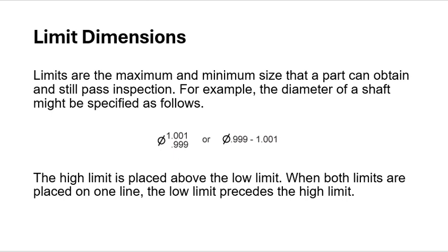So here, in this example, your part is a shaft, and of course your tolerance limits are for the diameter. Why do you know it's a diameter? Because of the symbol, and don't forget to review the symbols. Here, from here to here, it's telling you very formally where the limits are. So here is your min, and that's the max, and that's how we write it, linear. This one is vertical, so that's your min, and that's your max, and that's how we write it. Okay, so pay attention to this decimal. See that?